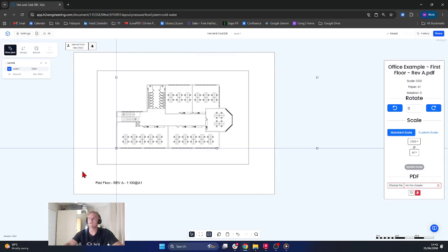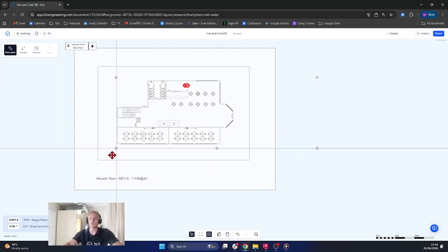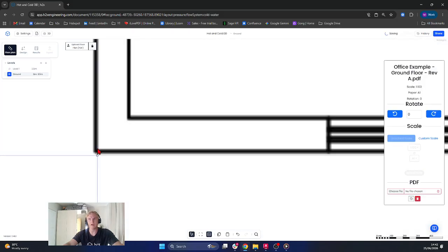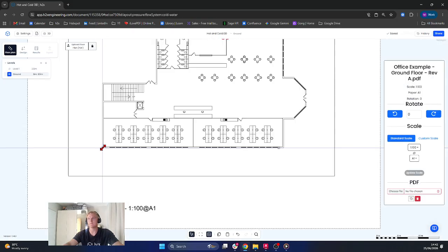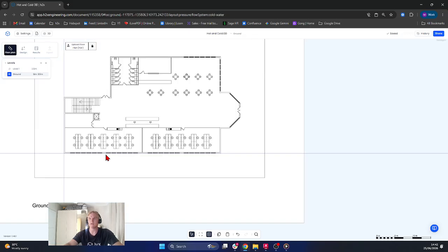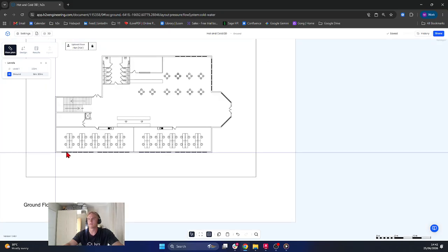Now, if you didn't align them and you wanted to use our AutoCAD export, you wouldn't be able to reference your AutoCAD drawing to anything that you haven't aligned that point to. So for example, the corner of that sheet might not appear on your AutoCAD model space. So I would always recommend aligning it if you are planning to take it out of h2x in any form other than our PDF drawing or reports.